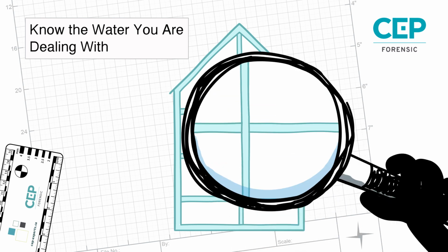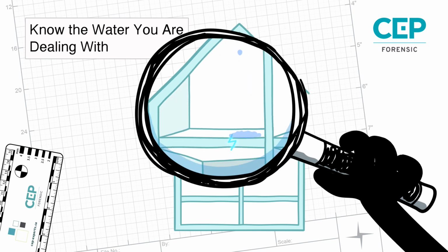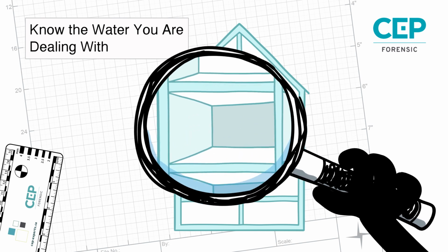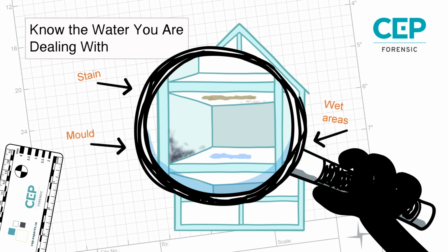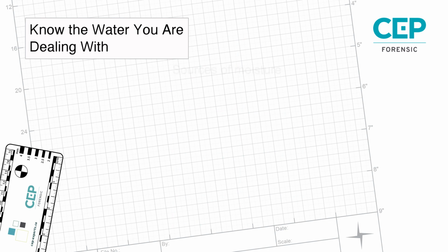Moisture damage can become apparent once a sufficient amount of moisture leaks into the interior, is retained by the building materials, and cannot be removed quickly. First signs of moisture damage can present themselves in the forms of stains, wet areas, and mold growth. Certain water losses are apparent, such as roof and basement leakage, while others may be less obvious, such as condensation.